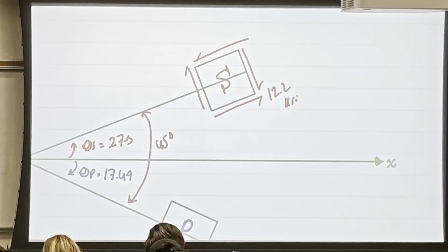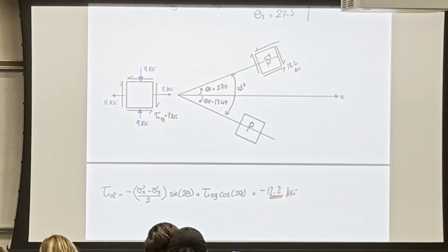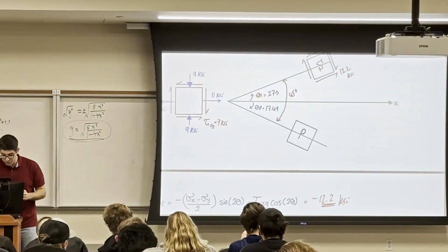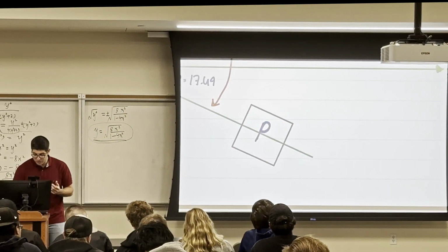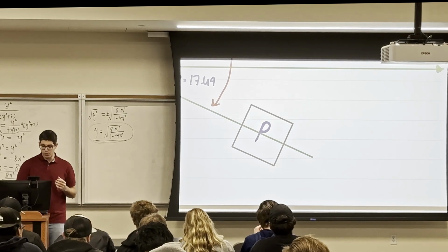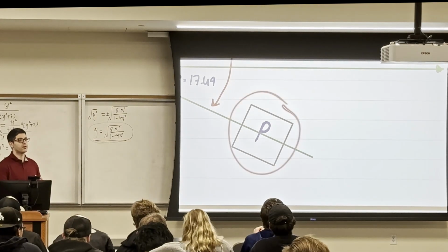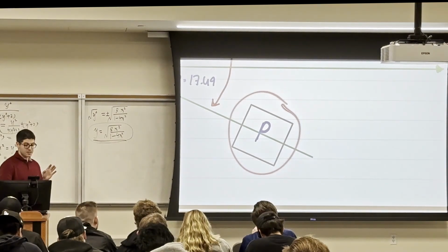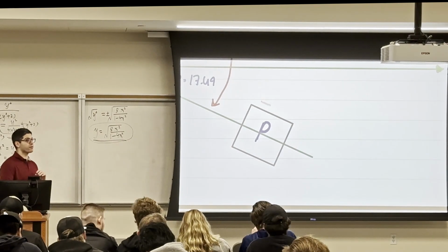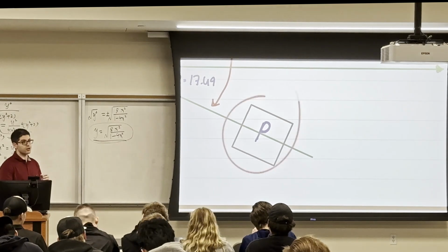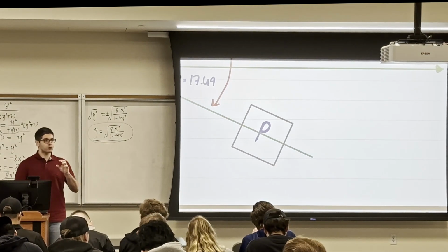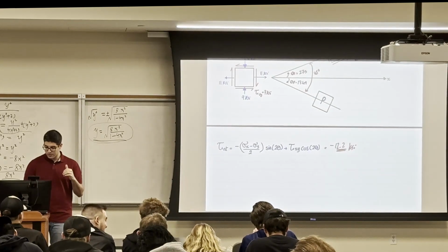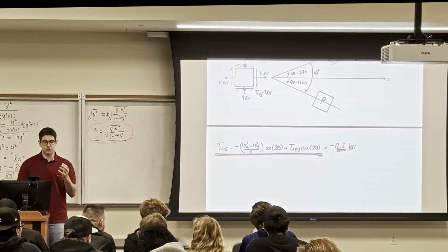Another question, I didn't continue this here. Another question will be, okay, now I figure out that this is theta p. First of all, will I have a shear stress here or no? I will not have a shear stress. Common mistake: some people put the principal shear stress. No, I proved to you mathematically there will be no shear stress. Okay, and also, if you took the angle of theta p and substitute in the tau equation, it will definitely be 0 if you want to double check.